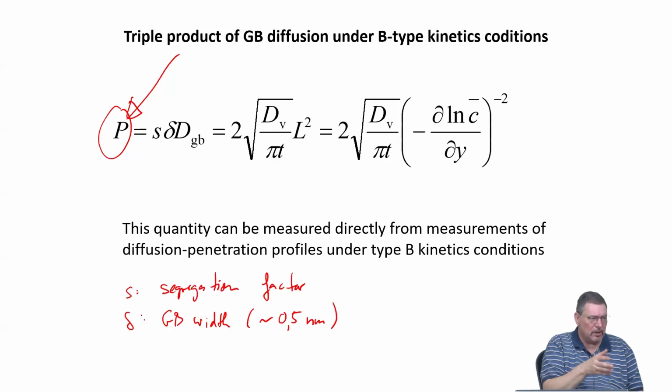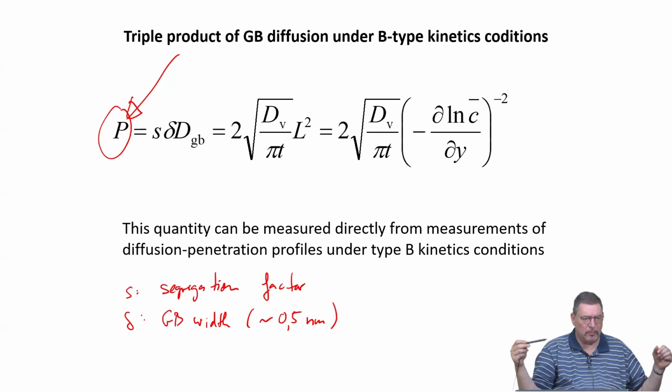Because when you look with atom probe tomography, this is a method you know, you have a very small tip, which has a radius of curvature of 10-20 nanometers, which you prepare from your material. And you apply to it, at low temperatures, a very strong electrical field with an electrical field gradient. So basically you field evaporate atoms from your tip.